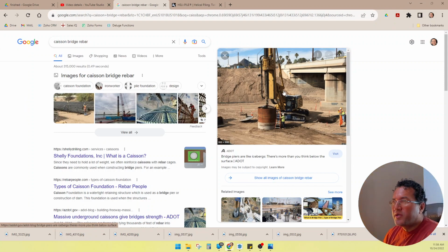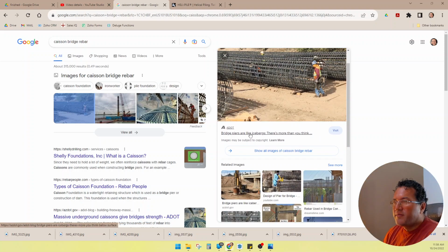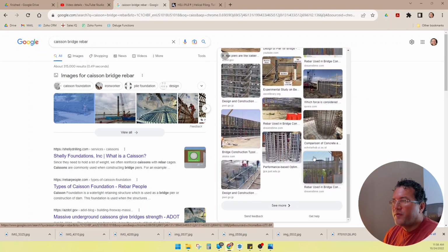This is what the drilling rig looks like whenever they're drilling these in place. Now this one has a concrete sleeve over it, meaning that they've had some problems with sloughing. When there's sloughing problems, they do have to start using a sleeve in order to stabilize the side. Okay, so you have a big giant excavator with a drill. Then you have this rebar cage sticking up.